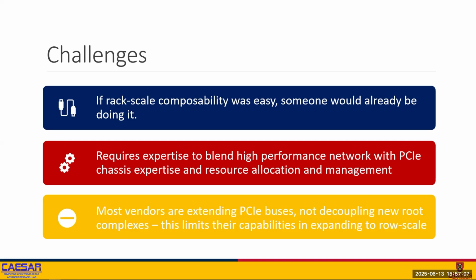So I won't bore you with the complexities of PCIe root complexes and how they end up getting shared, but there's a whole bunch of other things that you can do from a chassis perspective to provide those, think of them as the home. When something gets lost or something needs to get routed to a PCIe bus, not everything's on the same switch. It has to go back up to the root complex, and the root complex basically tells it where it's supposed to go and sends it back down. If that's out to the server, now we're taking light time back and forth in a row. Every time we want to communicate things, it's not efficient. We can do those things inside the chassis, though, to actually reflect stuff back into the existing chassis, and it significantly improves the performance as a whole. So this is something we've been working on as well.